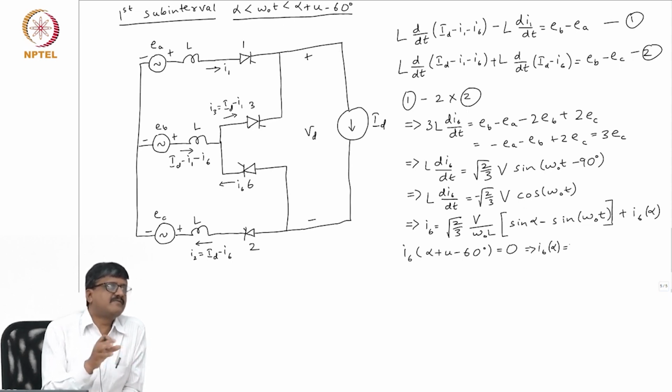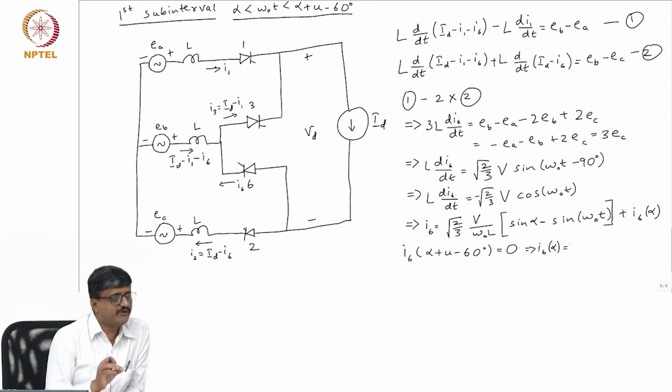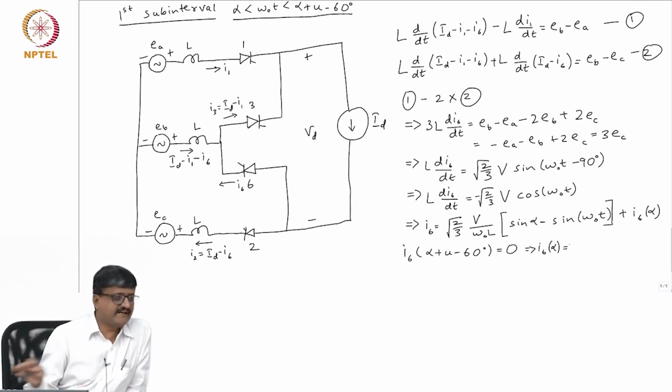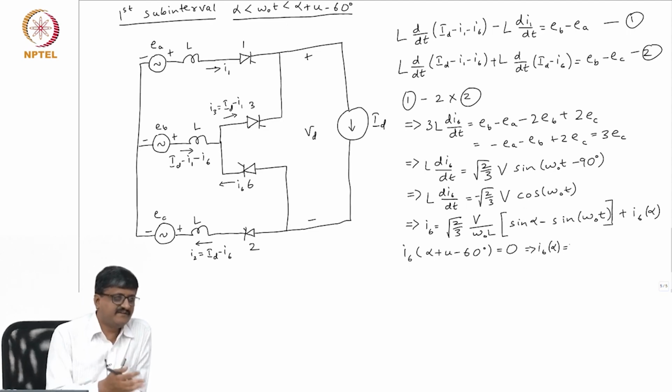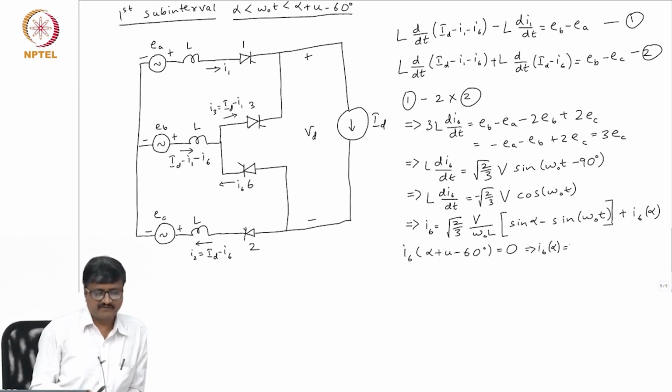So, we are not going to worry about some abnormal conditions which may exist for a few minutes in a year. Okay. So, what we are bothered about is normal operation. So, harmonic analysis is done only for normal operation, because we are going to design filters only for normal operation, not for abnormal operation. Okay. But we need to look at a few other quantities when it comes to abnormal operation. So, only those things we will be doing. So, obviously, we will not be doing any Fourier analysis for abnormal operation. Okay. So, normal operation itself, I mean it's sufficiently laborious. I don't know if you have tried, you would have noticed that. Okay.